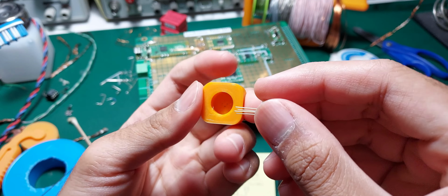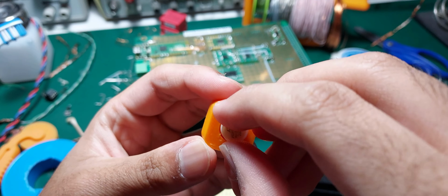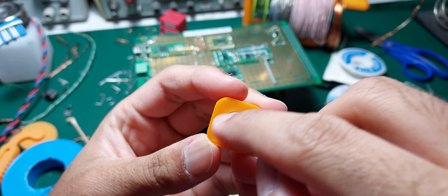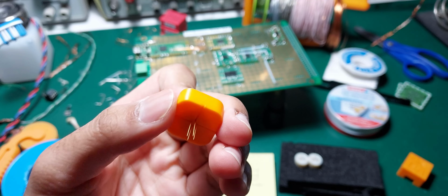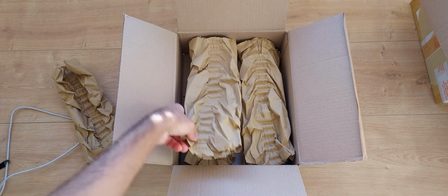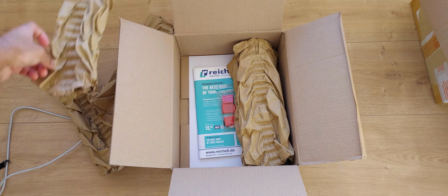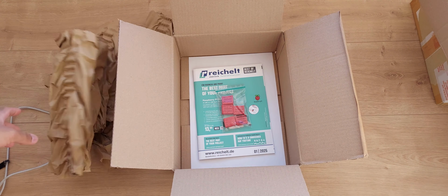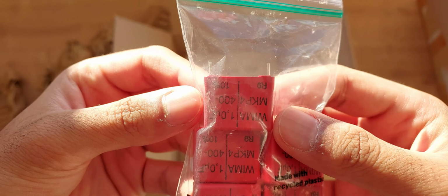The ADR itself is designed to be surface mounted to the PCB. I thought I was being clever by using this 3D printed jig to bend the leads perfectly, but if I had done so, I would have no way of getting the ADR out. Since I was going all out, I decided to splurge on some Vima MKP polypropylene. Film capacitors are the only real choice for precision applications that need a relatively large capacitance.